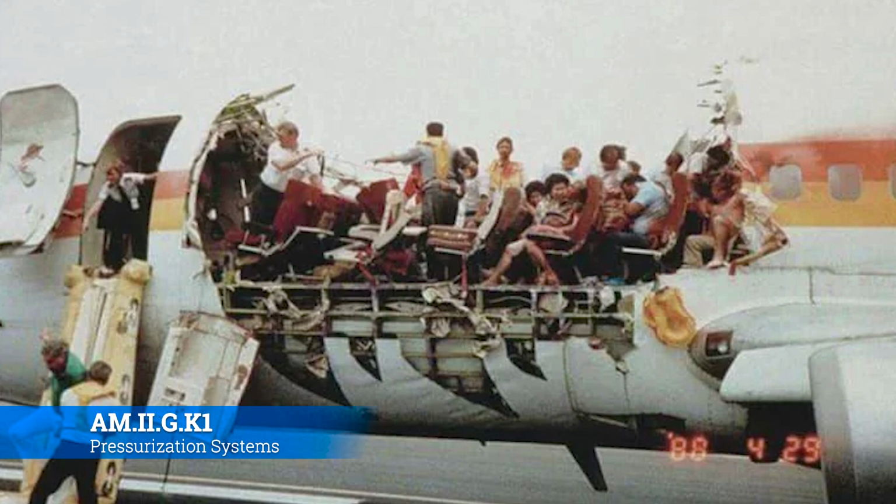aging aircraft program that looks for problems like this before they happen. They study aircraft that have gone through what they call multiple cycles, so pressurization, depressurization, pressurization, depressurization. That's a cycle. Anytime you cycle metal like that, you get metal fatigue. So when you get to work and you come up with an NDI inspection, you're going to eddy current this section of the fuselage, or these pieces. That's why you're looking for problems before they turn into an Aloha Air 243 and cause massive decompression.